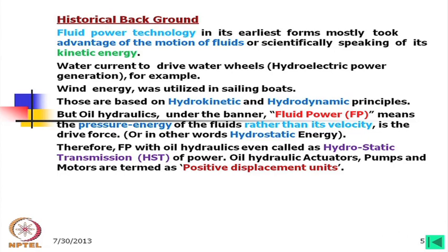Now, here I would like to explain. Let us consider an ordinary hydraulic pump, a centrifugal pump. There we are using kinetic energy. When the impeller inside is rotating, a suction head is generated through which the fluid comes in, and that fluid is energized by the velocity, and then it is discharged at a pressure which may not be very high, but still we can supply the fluid with a certain pressure.